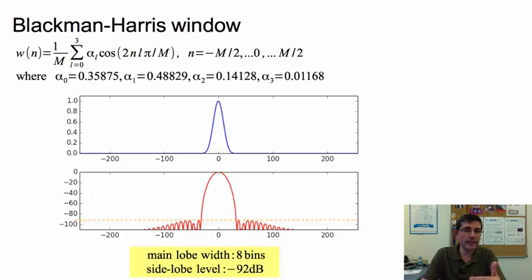And if we think about it in terms of signal to noise ratio, which is a very important factor in digital signals, 92 decibels is basically below the noise floor of 16 bits of the kind of signals that we deal with. So basically that means that the side lobes, if we consider them as artifacts or as noise, are not heard. In other windows, we could say that these side lobes are artifacts that can be heard. Anyway, again, we will come back to that.